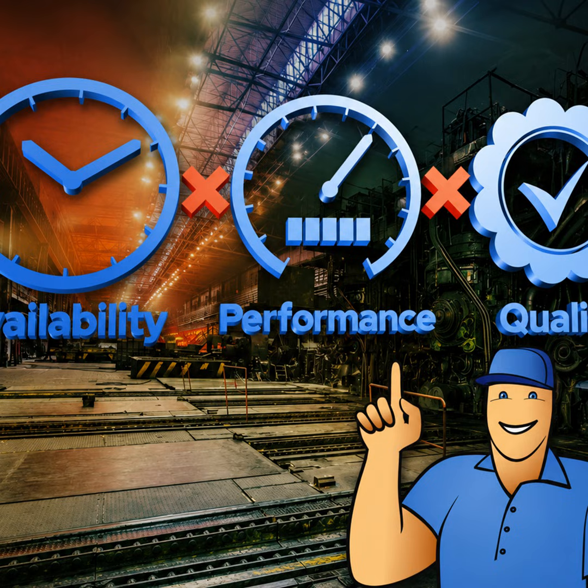OEE shows the gap between the theoretical output of a machine and its actual output. It helps determine where bottlenecks or inefficiencies exist in your production lines. It's often used together with capacity utilization calculations to develop initiatives that improve OEE in your manufacturing process and increase profitability. What's a good OEE score?